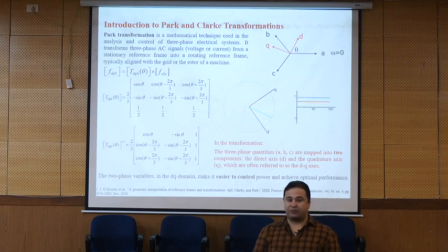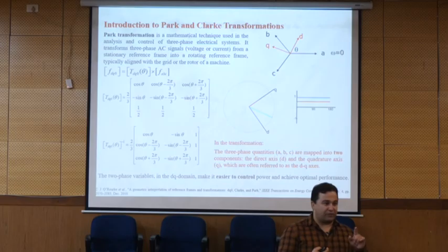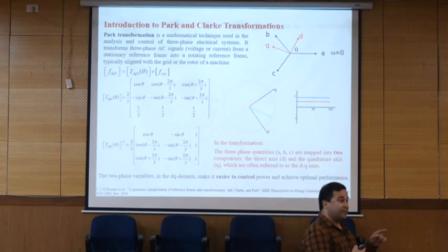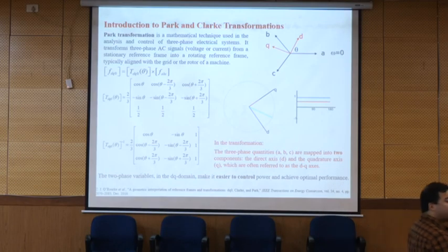Then the distribution company said that, no, you are not allowed to be connected. You should compensate your system, your load. Otherwise, you should pay 10 times penalty, because you make the grid unstable and then it affects the other loads also. So you cannot. So what should we do?